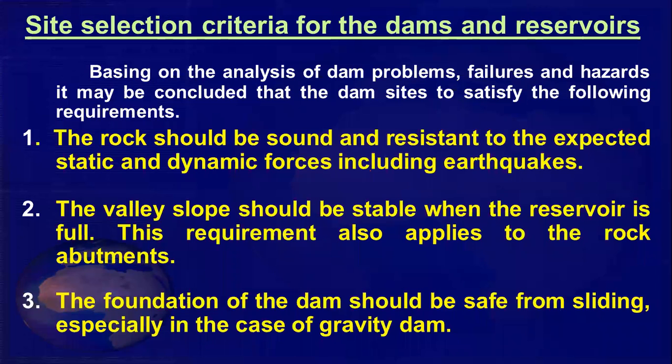Which are the dynamic forces? Force due to the earthquake, that is the seismic force, is the dynamic force. So it has to resist that. So ultimately your rock should have the higher strength. Then the valley slope should be stable when the reservoir is full.